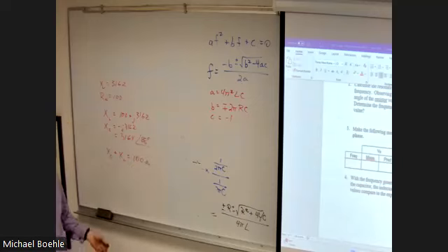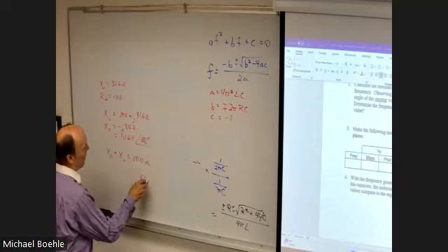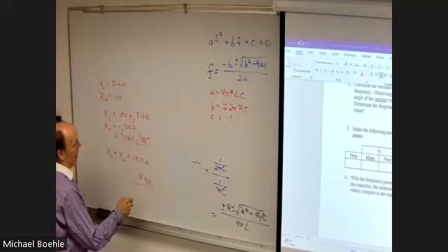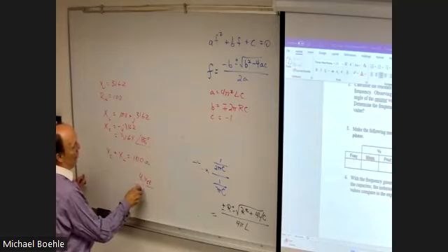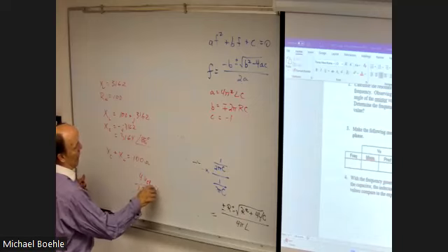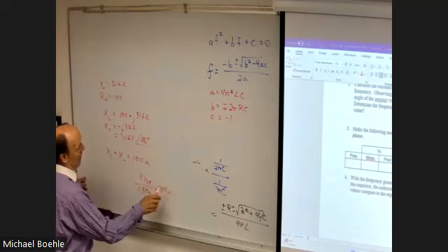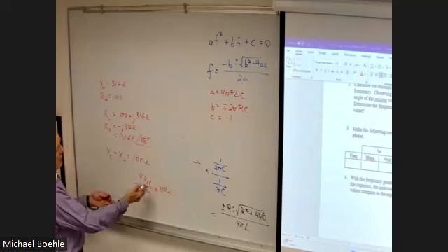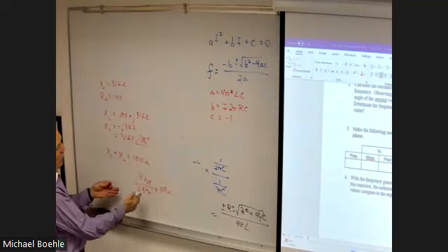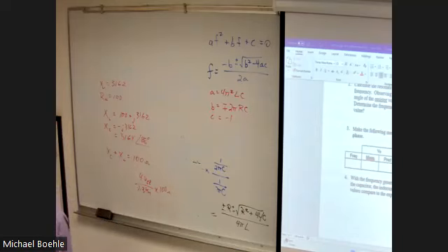So whatever current we have, if we have 4 volts peak to peak, and we have a total resistance of about 1.3 kilo ohms, you multiply that by 100 ohms, you're going to have a little less than 1/10 of 4. So you're going to have around a third of a volt, just rounding my numbers. So you will see some voltage.